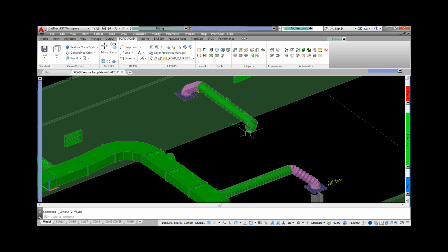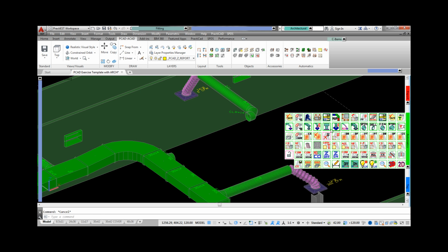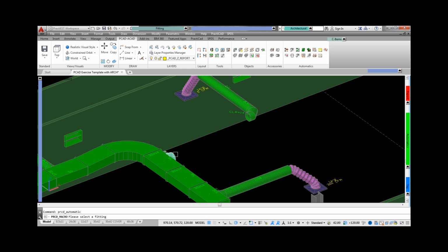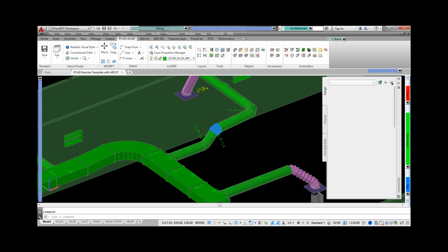Here we're going to delete pipe, then click on the elbow and raise the duct line forward to 15 foot. Then we're going to use an auto route tool to route two 45-degree elbows between the points. We can even click on the elbow after the change and change the slope of the line by adjusting the angle. In this next example, we're going to show you how we can edit full duct lines in either direction.